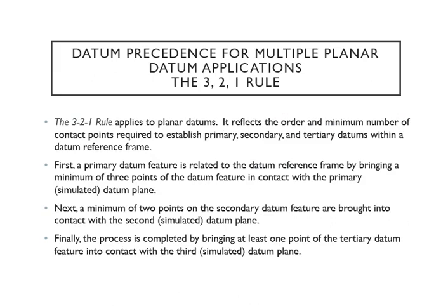All right. So now after you finish putting in order primary, secondary, tertiary, we're going to give the number of contacts. So primary, you need 3, secondary 2, and then tertiary 1. I've already talked about that in the initial slides. So if I ask you how many contact points do I need for primary datum, it is 3. For secondary, 2 contacts, and tertiary, a single contact.